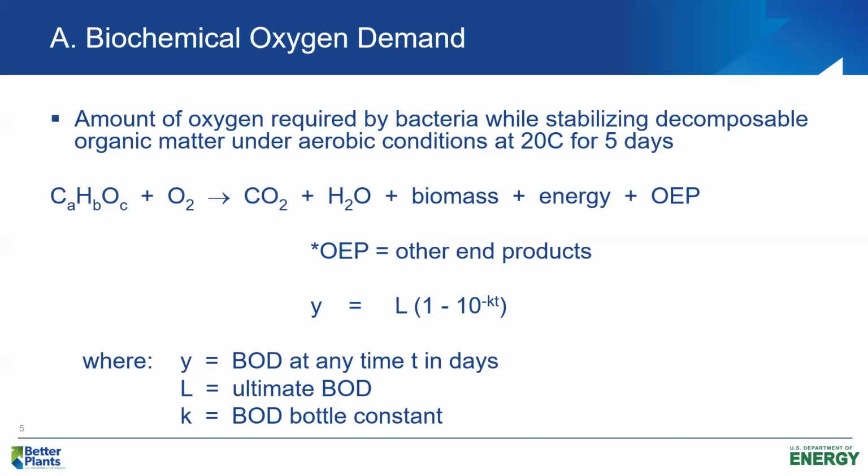Now, we run the BOD 5, that's the standard test. And the reason we do that is because in England, when it was developed over 100 years ago, there was no point, I believe, in the Thames River that if you discharge raw sewage into the Thames River, the longest it took to get to the Atlantic Ocean or the English Channel was 5 days. So they were only concerned about that oxygen demand for 5 days in the Thames River. So they ran the BOD 5.